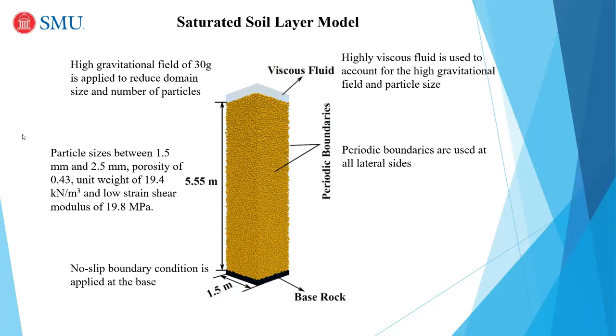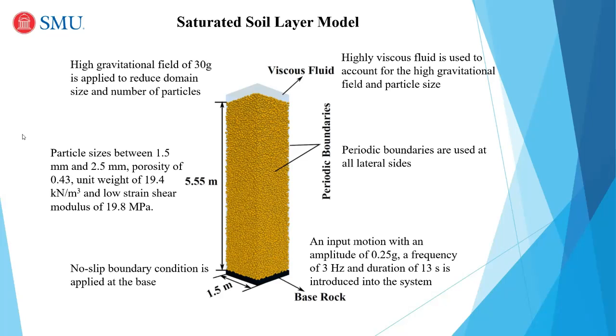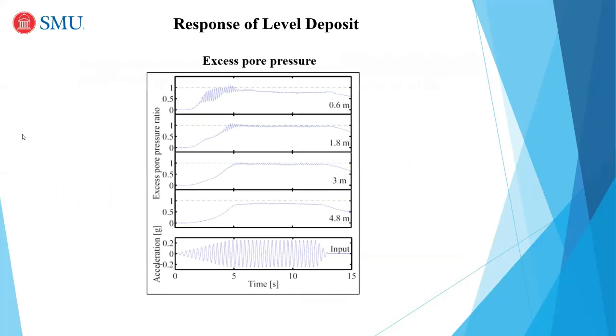We apply seismic motion to the base of the deposit here. In this case, we just apply very nice sinusoidal motion so that we don't complicate the response too much by applying a random quick motion. But we can if we want. So again, we have so many results coming from any single simulation, but to focus on key things, key mechanisms. So I know we are in Dallas, we are in Texas. We don't really worry much about something like soil liquefaction, but it's interesting to at least understand what happens here, because the idea is to learn how an advanced modeling like this can capture a complex phenomena like liquefaction.